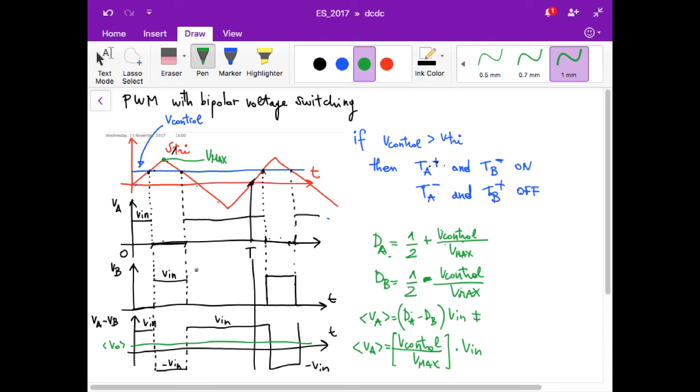And you can use exactly the same type of circuit, but instead of having this type of filtering, and instead of extracting only the DC voltage, in that case what you want to do is to have a rectangular wave with a duty cycle equal to 1/2, so almost a square wave.